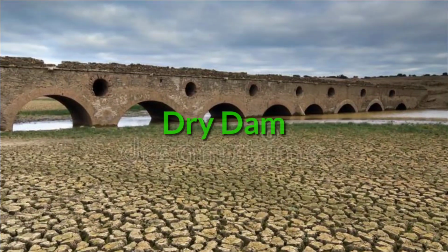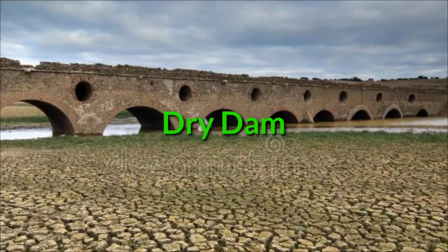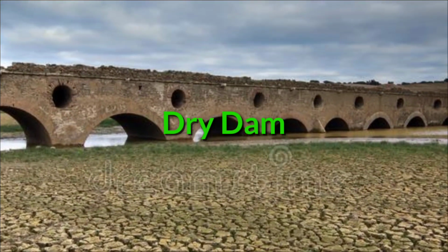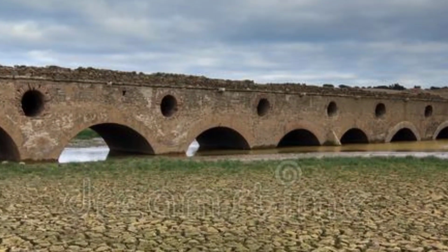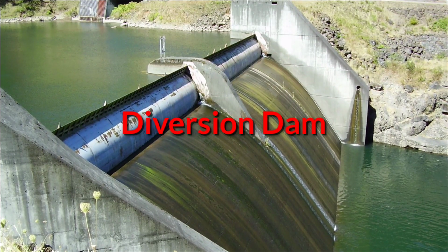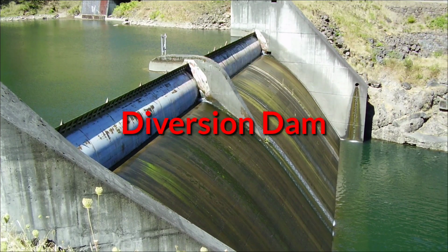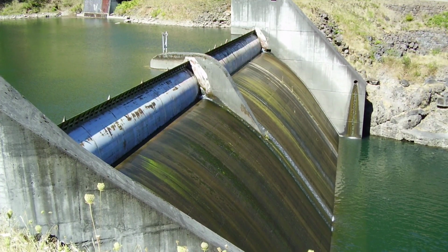Next one is the dry dam. A dry dam is also known as a flood retarding structure. It is designed to control flooding. It normally holds back no water and allows the channel to flow freely, except during periods of intense flow which would otherwise cause flooding at downstream sites. Next one is the diversionary dam. A diversionary dam is designed to divert all or a portion of the flow of a river from its natural course. The water may be redirected into a canal or a tunnel for irrigation or hydroelectric power generation.